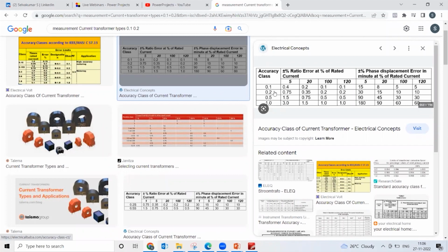Similarly, when you have some power plants in starting stages, or the plant is off and you are consuming only the auxiliary power from the grid. Wherever you have a power plant and you are consuming only for the auxiliary, this scenario can occur, where you will face a challenge that CTs are not accurate enough and they are not driving the values.